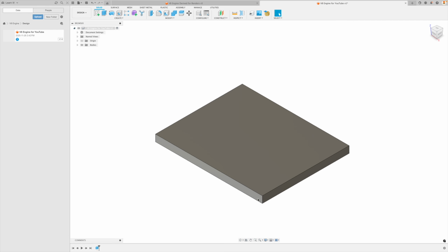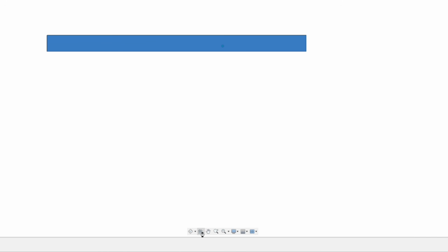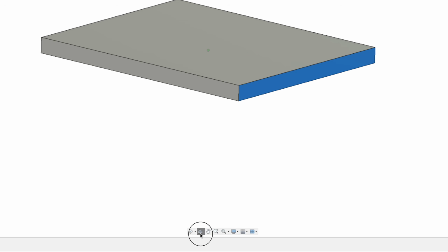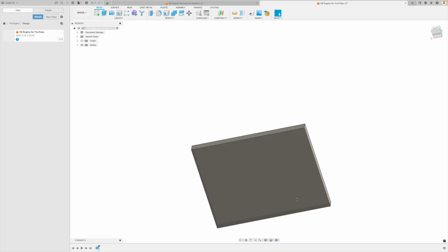But yeah, what we can do is always pick a face, and then we can select the look at, and it will go normal to that face. Let's just go on over here, look at, perfect. Now I want to show you one thing. How am I doing this right now?